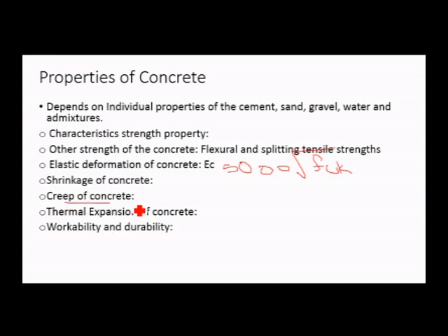Creep is another time dependent deformation of concrete, by which it continues to deform, usually under compressive stress. The creep strain recovers partly when stresses are released, and this long term deflection is added to the short term deflection to get the total deflection of the structure.